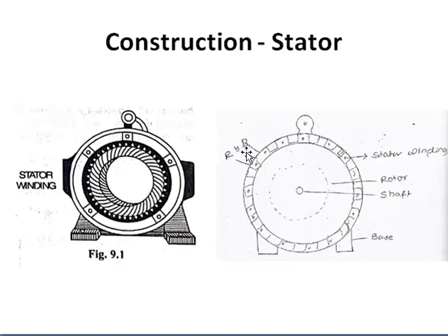So now what happened? We have given three-phase supply to the stator winding, and the stator winding will start carrying current, and those three-phase currents in the three phases will create a rotating magnetic field. That magnetic field will start rotating in this space. We have a very small air gap, and through that air gap it cuts the conductors on the rotor winding. Initially the rotor is static. The rotor is not moving. What is moving? The magnetic field is moving. When the rotor winding and its conductors are static and the magnetic field is rotating, each conductor on the rotor winding will start cutting the magnetic flux.